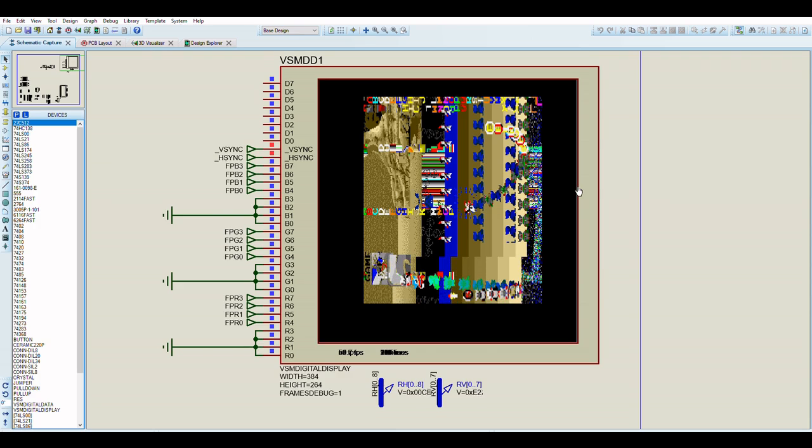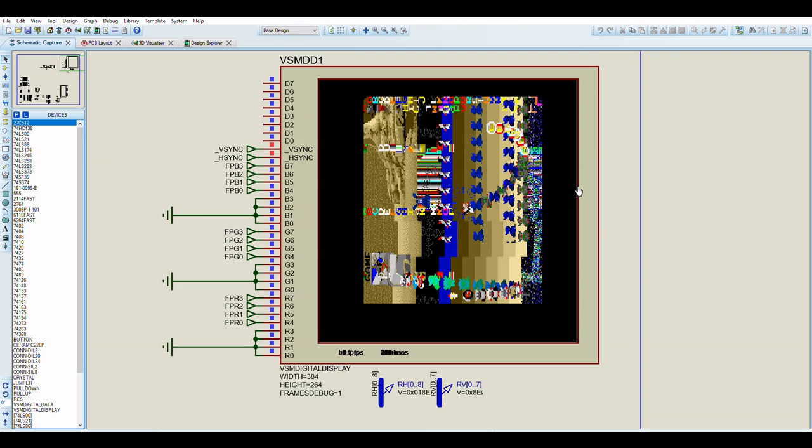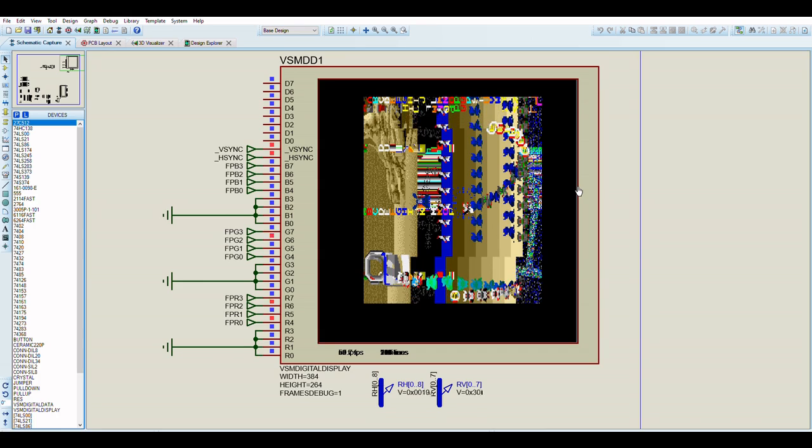I can do similar things with the Mode 7 registers by exploiting the fact that I can reset the internal counters independently, and I can force them to 0 independently as well, which also gives me a whole range of extra intriguing effects based on per pixel horizontal or vertical raster position.